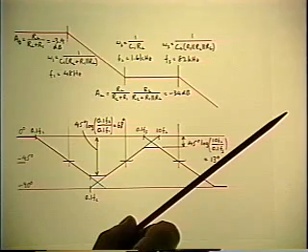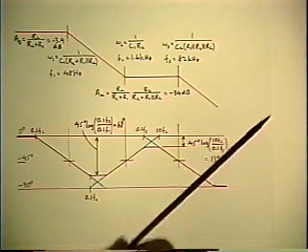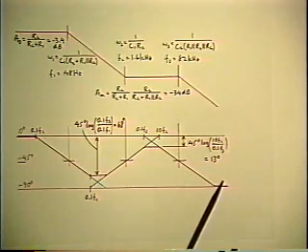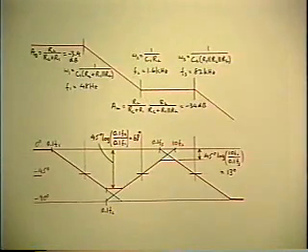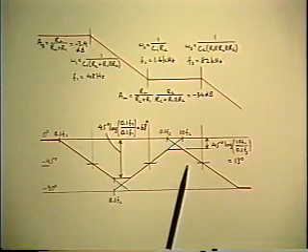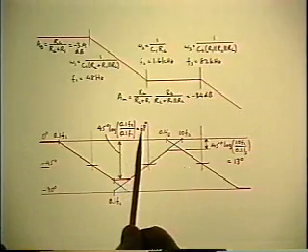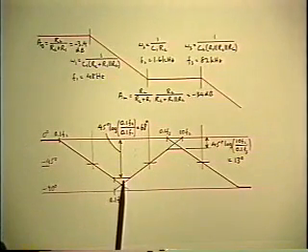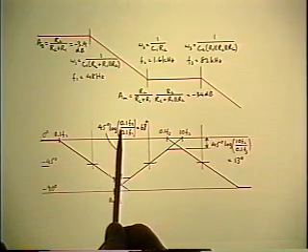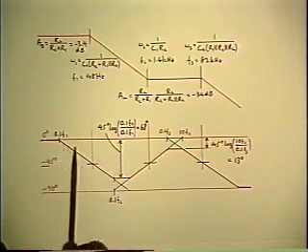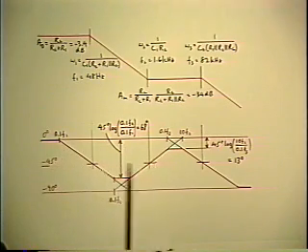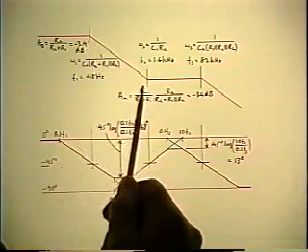So you simply do the same problem twice now to make both of the maximum phase lags not greater than 50 degrees. And of course, it's easy to do that because you start with a known value of the maximum phase lag, and according to that little handbook formula we had earlier on, you can translate that directly into the required ratio of these two corner frequencies, which is the first pole and the zero.